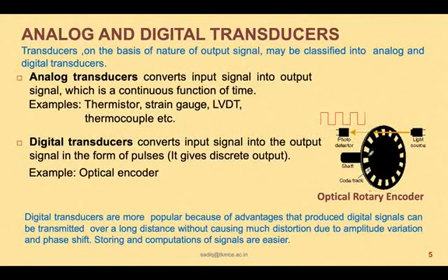Now imagine that with the light source and the detector stationary, a shaft mounted with the encoder rotates. When the shaft rotates, the encoder will also rotate. When the encoder rotates, the light from the light source will intermittently fall on the detector whenever there is an opening coming between the light source and the detector. Whenever light falls on it, a pulse is generated by the photodetector.